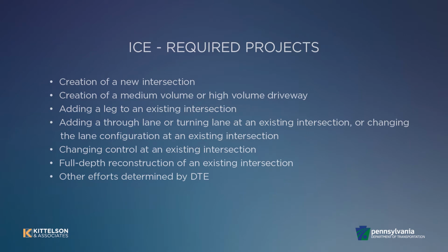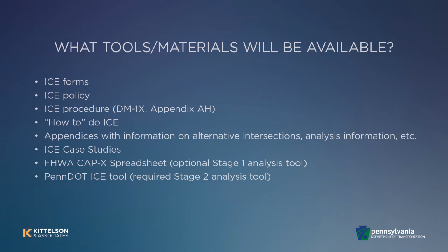ICE is required for any project that creates a new intersection, any project that creates a medium or high volume driveway, any project that adds a leg to an existing intersection, any project that adds a through lane or a turning lane at an existing intersection or changes lane configuration, any project that changes control at an intersection, such as adding a traffic signal, any project that is full-depth reconstruction of an existing intersection, or other projects as determined by the district traffic engineer.